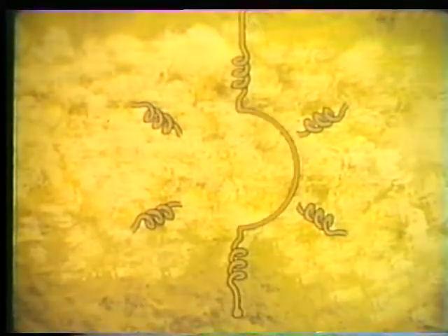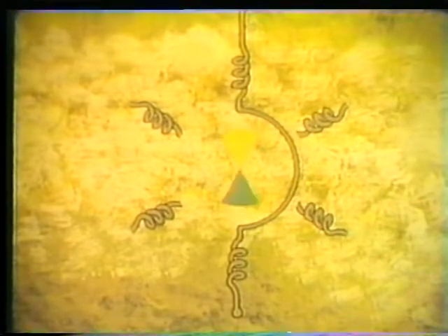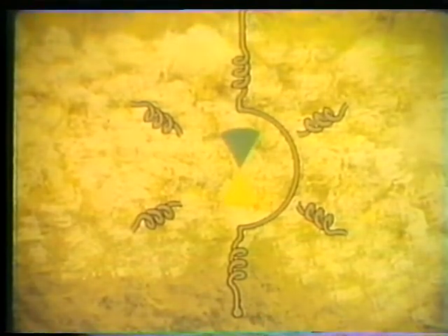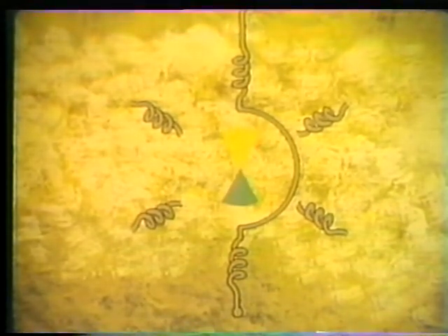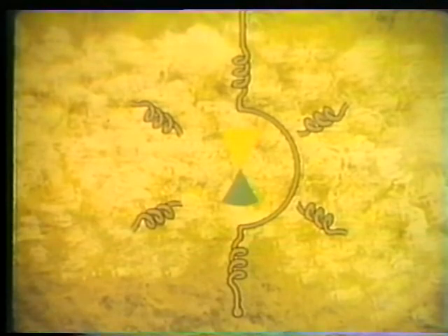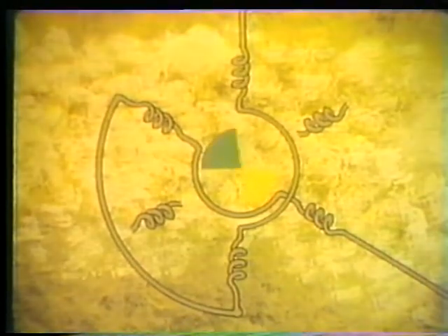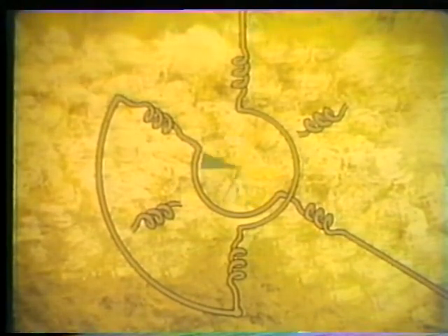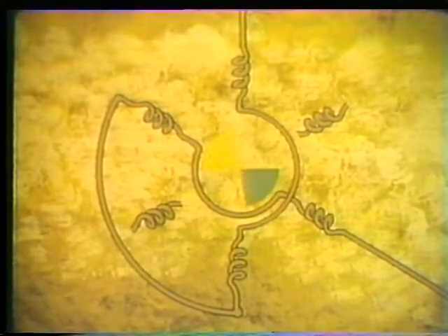And when the first coil pair is energized, current flows through it. This current produces a magnetic field between the coils. The magnetic field changes with the current, and the north and south poles of the coils reverse with the change in current direction. The second phase current flows through the second coil pair, but the first phase is further along in its current cycle, so the magnetic field generated by each coil pair differs in intensity.